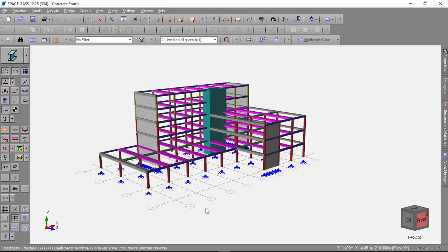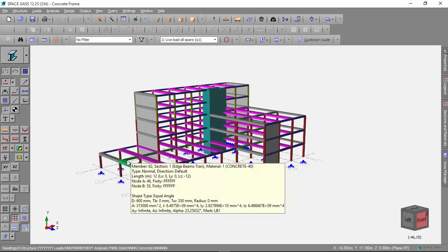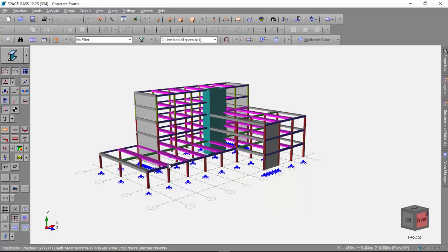So as in the column design module, you need to specify your cross section first. The design module won't change your cross section, it will only specify the reinforcement. This model has got slabs spanning two-way, and we haven't actually modelled the slabs, we've just modelled the beams as T-beams and L-beams that are supporting the slabs, and applied the slab loads as area loads